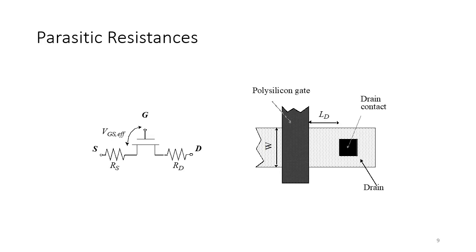Now during the conduction and during the MOS formation, there are some parasitic resistances that occur between the polysilicon and the drain region that will affect the operation of the device, and that will also increase the delay.